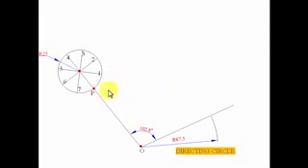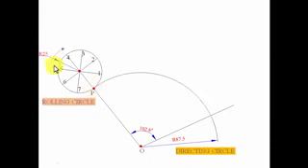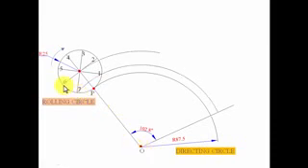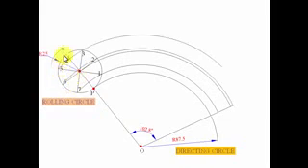Alright, now let's have the arcs with O as center and with OP as radius. I'm going to draw an arc right now, something like this. So this rolling circle is rolling in the clockwise sense, and with O as center and with O7 as the radius, I'm going to make an arc here again. Now with O6 as the center, and with O5, with O4. Alright, so these are the arcs.